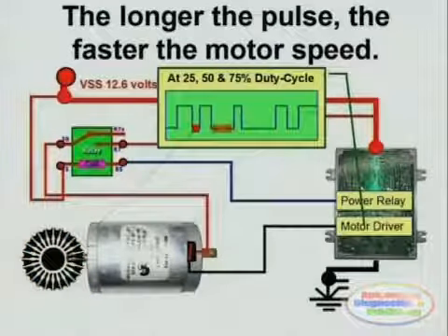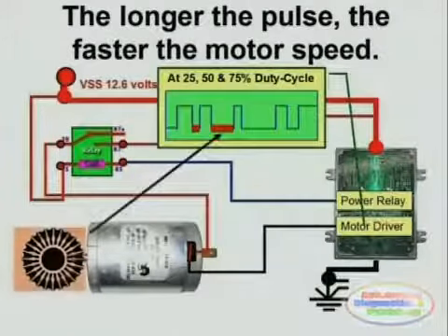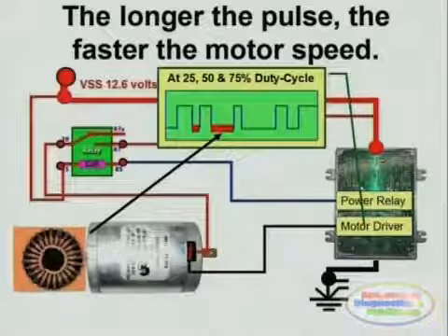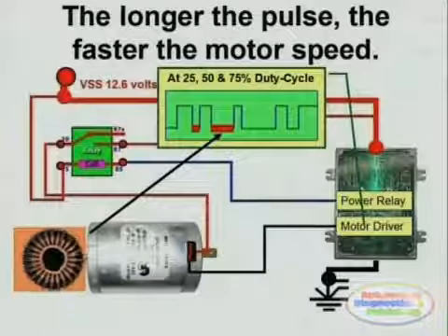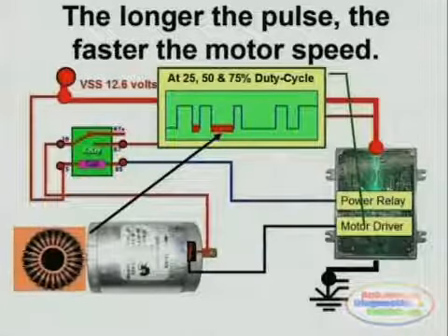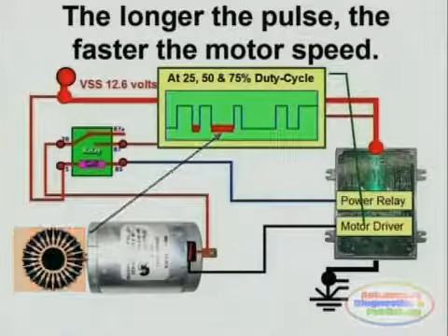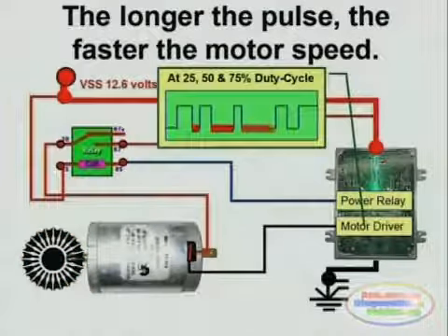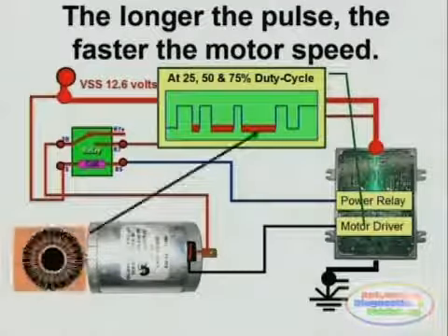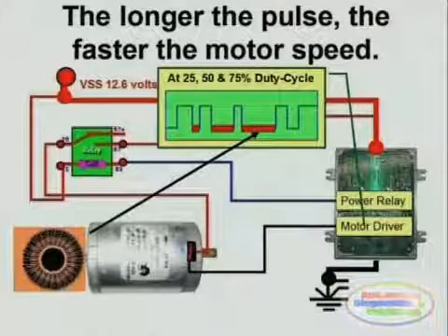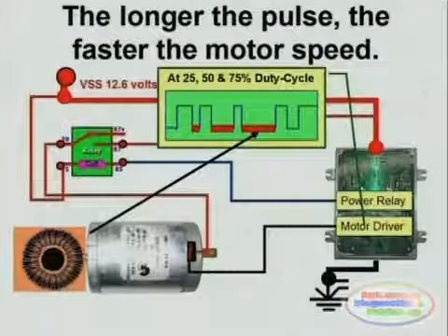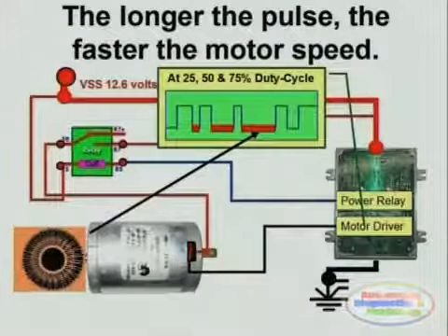At cruise speeds, for example, you will need maybe a 50 to 60% duty cycle for the fuel pump, and this we can see on the screen. And during extremely loaded conditions, as for example when towing, you will need maybe a 75 to 90% duty cycle, making the flow of fuel through the fuel rail a lot higher.